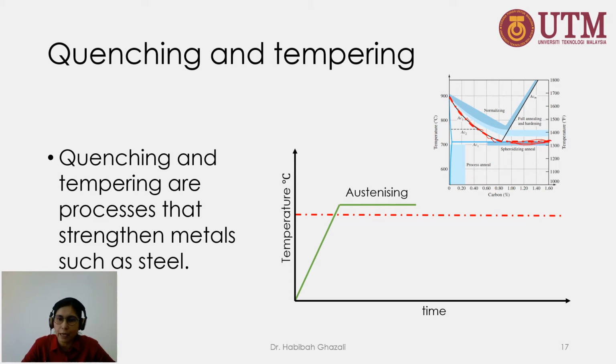I know you might be asking, the microstructure won't be transformed to fully austenite if you heat up above this line, only above this line. Yes, you're correct, but that's how you conduct it for hypereutectoid steel. This is to avoid large grains of austenite being formed. So if you heat up above this line, you will allow a lot more diffusion of atoms to happen.